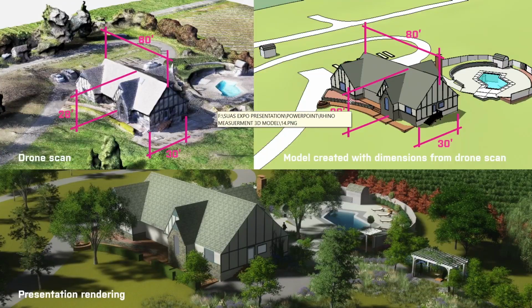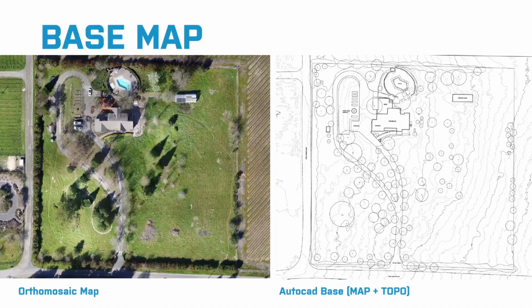And did you go out and field check any of them? That would be my anxiety, that it says it's 30 feet, but it turns out it's not. So I took about three measurements on this base plan. I went to the corner and measured the width of this greenhouse. I measured the pool, because I knew I could clearly see it from the aerial photo and it wouldn't be disrupted by tree lines or anything. And then I measured the width of the driveway in the front. So I was able to confirm that these were all accurate when I got the eventual output of the digital model.